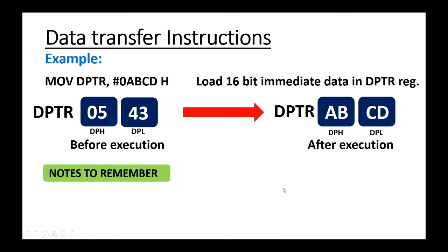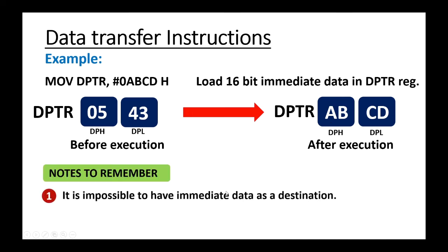So always remember that we cannot have an immediate data as a destination. Since it is a move instruction, data is moved or copied from source to destination. So you cannot put immediate data as a destination.